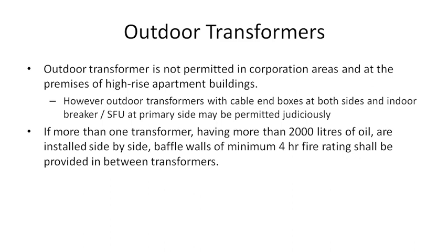This applies to oil-filled transformers where the content of oil is greater than 2,000 liters per transformer. If you go to a 110 kV yard, normally they are not using 3-phase transformers. They might be using 3 single-phase transformers, or a bank of transformers. Between these transformers, a wall has been built as if to separate them so they cannot see each other. So that is your fire wall, actually.